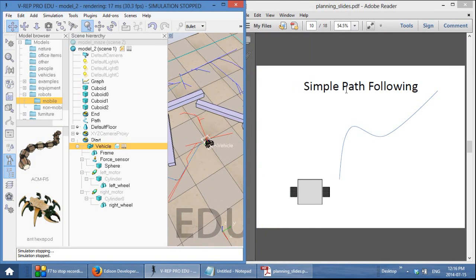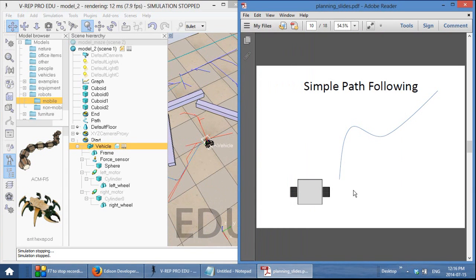So now, what is our strategy here to control the robot? Essentially, this is what we currently have. We have a differential drive robot at some sort of a path. So now we have to decide, how do we follow the path? We would like the robot to go forward at a constant velocity, which we call vrob. We also have functions within vrep to find a point on a path. So what we do is draw a vector from our robot to our path point, and this can tell us what exactly we have to do to navigate towards the path point.